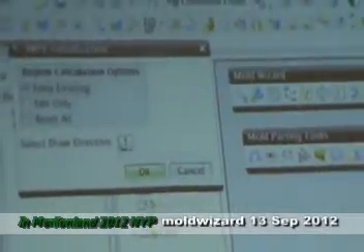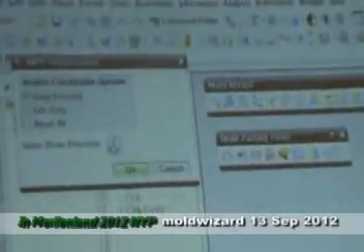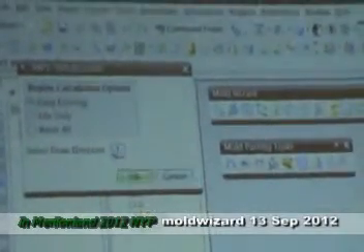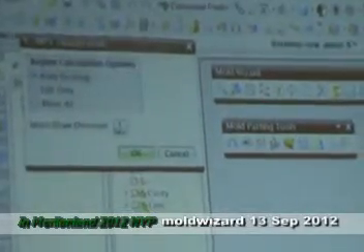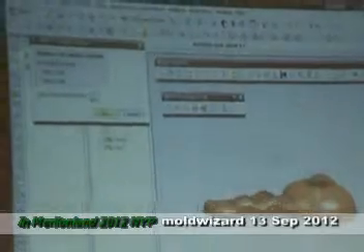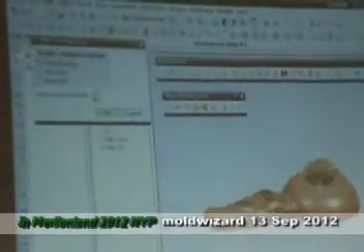So more cutting tools. The first one, analyze the region. So where the draw direction, I mean the ejection direction. I will define this will be the negative X. So you can see our white color virtual vector.